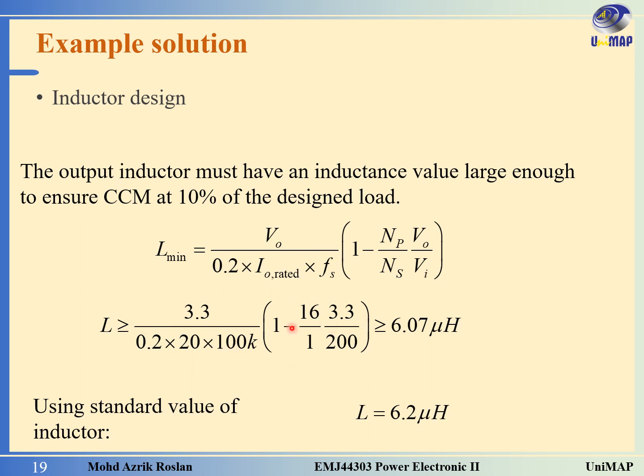When we calculate this, our minimum value is 6.07 microhenry. Looking at the table for standard inductor values, the nearest value bigger than this one is 6.2 microhenry.